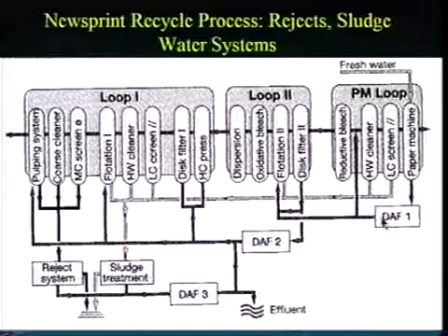But we also take some of that, all that excess water, which is relatively clean. So that excess water is actually going to go into loop 2, actually into the flotation step. All right, so we're using our water from our paper machine. That's going to be the cleanest in loop 2, and that's going to go into our flotation. And so you see we're going to add that water in this direction. The pulp's going that direction, the water's going in this direction. So it's countercurrent pulp and water flow.